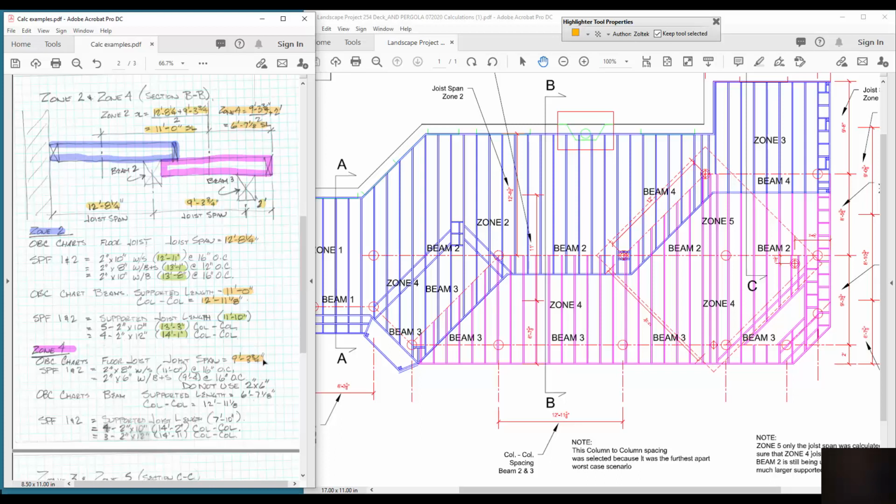There we go. Looking at the tables and charts, there's 2 that are available to us. There's actually 3. There's a 2 by 6, but note this, and I'm going to highlight this with a very different color so it stands out. Do not use 2x6. Okay, we're not going to use any 2x6s in our project. We're going to stick with 2x10s, 2x12s, 2x8s. We don't use any 2x6s. That's for a very, very small platform. There's no point. Plus, the variation of the size is too much to work with. So that's why I've got that note in here.